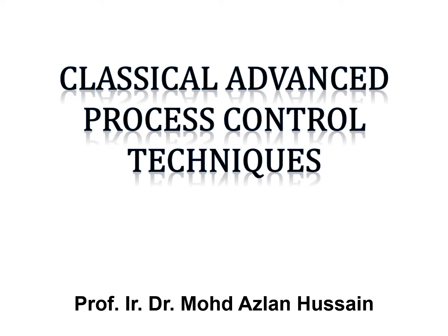Now we go to the next one, feed-forward control. We still define it as classical, because it's just a slight extension of the normal conventional process control that uses the PID system we have seen before. It is a slight extension with a combination of PID and a feed-forward model technique, as we will see next.